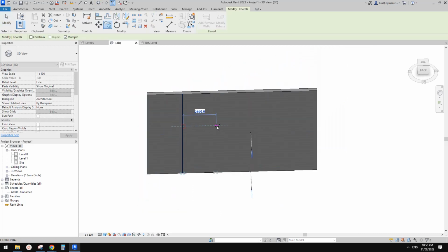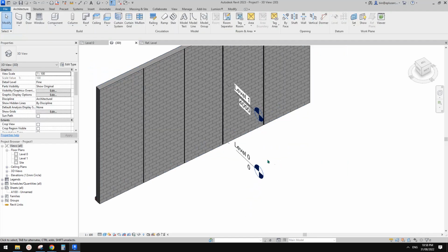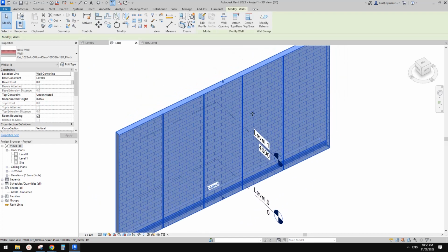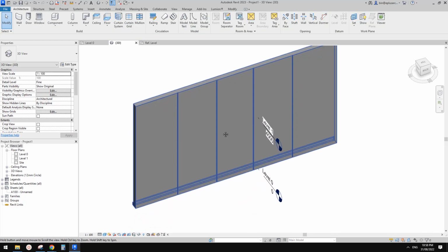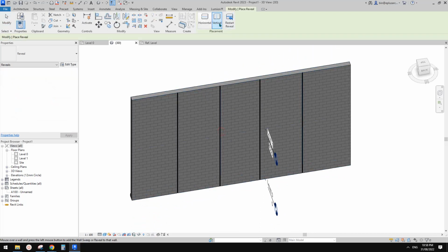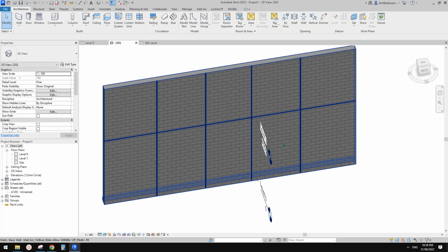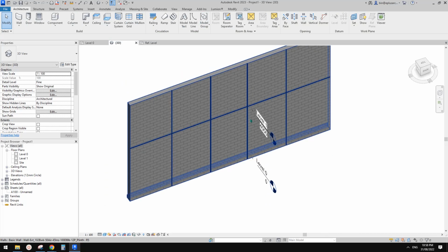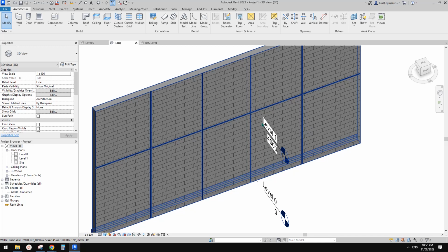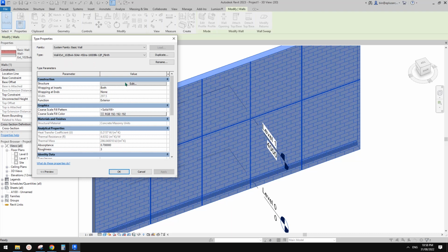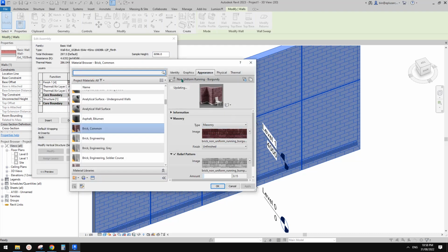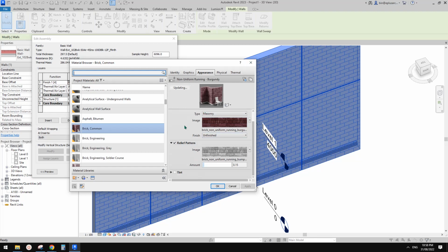You can just copy this to add certain spacing, and then represent the gap between those precast concrete panels. So yeah, if this can be useful, and you can also place them horizontally. This will create a better result than only using the relief material or bump or whatever you have here.